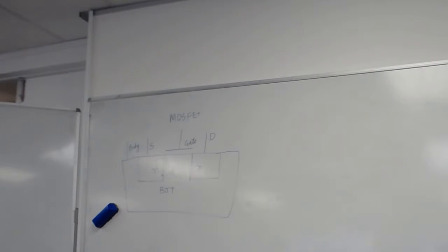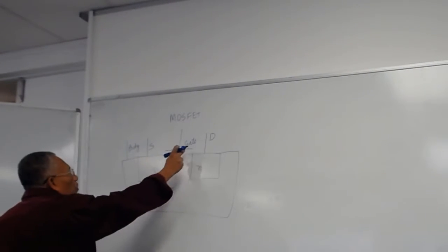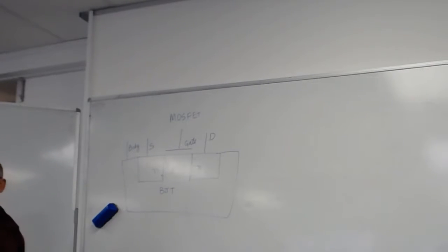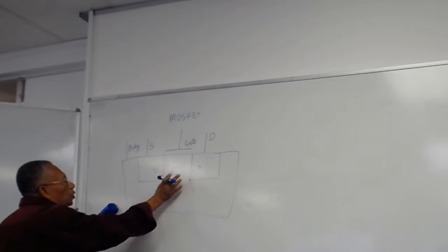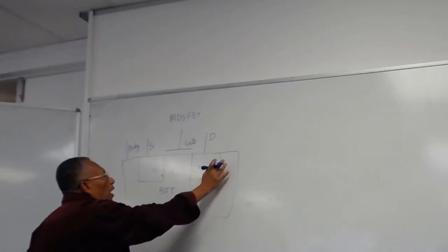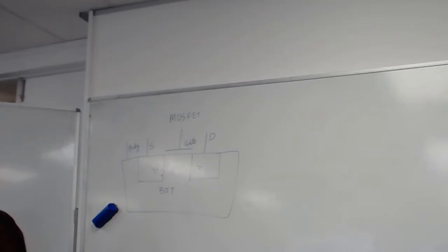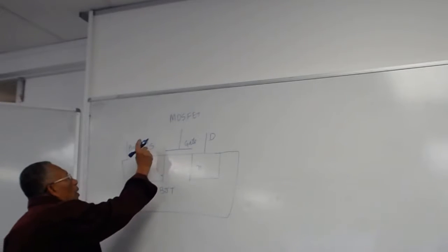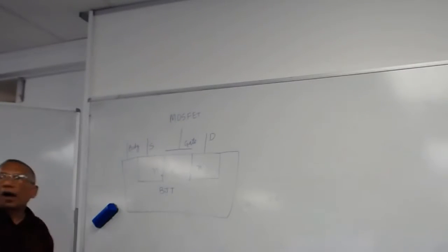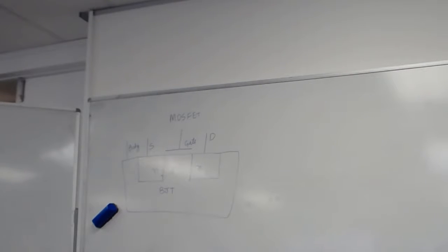Okay. So you have an NPN, then you put a capacitor on top of it, a gate here, and then your P, allow the P to continue across all over the place beyond these two regions. So then this is your MOSFET. So you have 1 terminal, 2 terminal, 3 terminal, 4 terminal. 4 terminals. So this is just an introduction to how you could go into a MOSFET starting from a BJT.